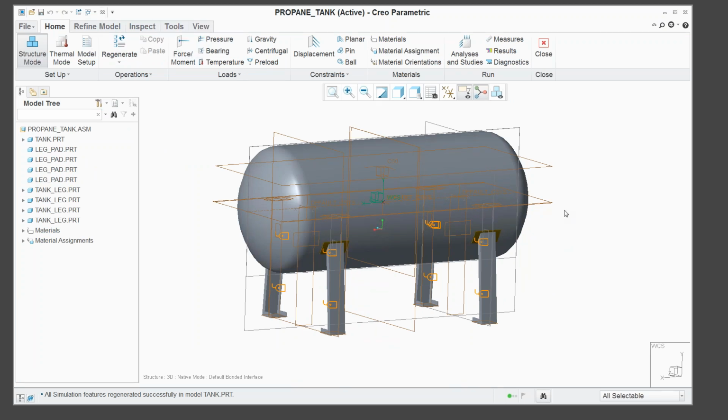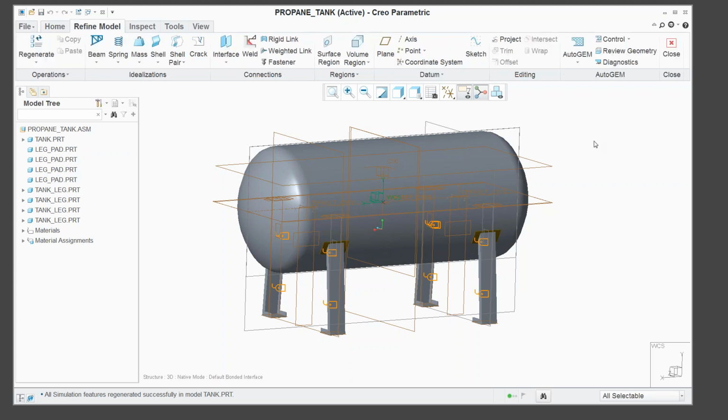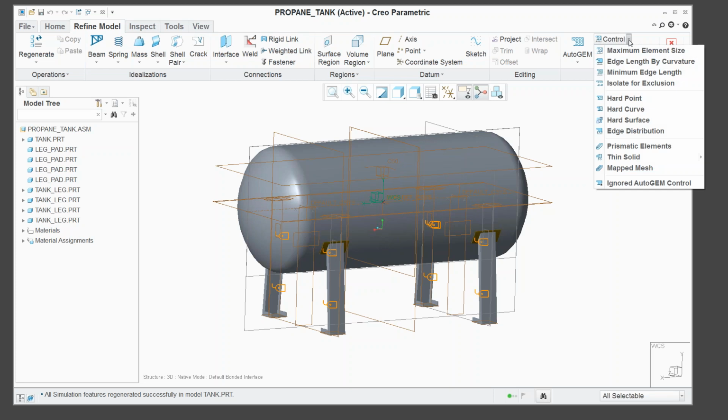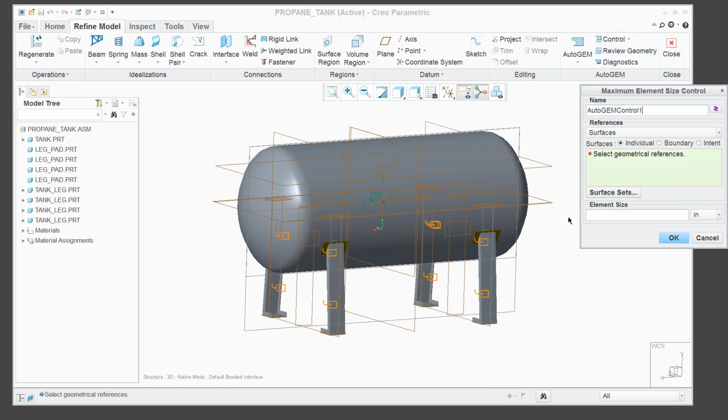All right, now the next thing I'm going to do is recognize that the mesh that we created was not good, and we really need to apply some refinement. So it's pretty simple to do in the newer version of Creo here. The easiest way to do it is to just limit element size. That also improves aspect ratio, improves the transitions and generally gives you better mesh. It's easy to do. So I'm going to set maximum element size.